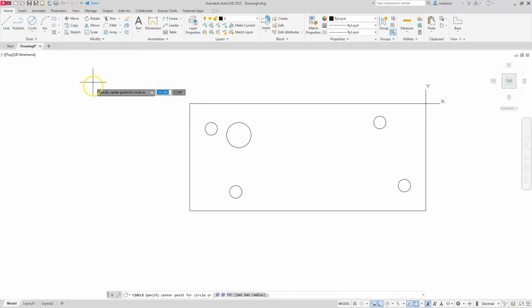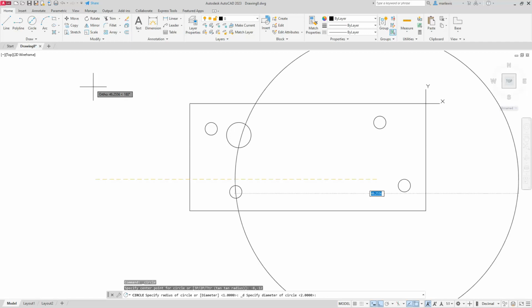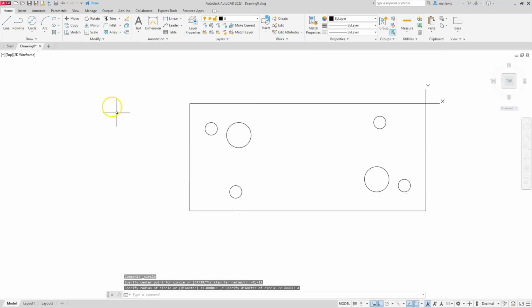Go ahead and create your circle center diameter. -8, comma, and now I can do the math and figure out that I'm going down a -12. Enter, and then give it its diameter, which in this case is 4. And like I always say, go ahead and make sure that you move your UCS backwards to the world coordinate system. All right, and this one is done.